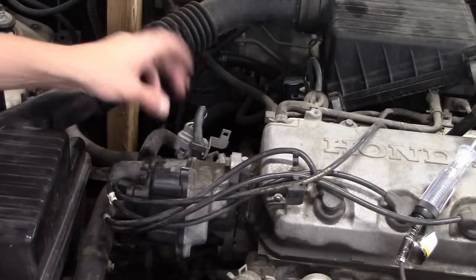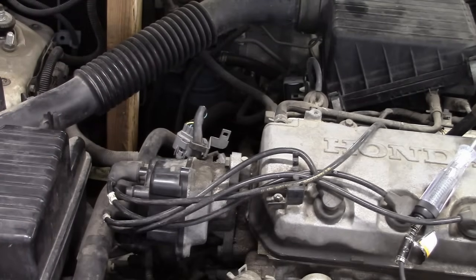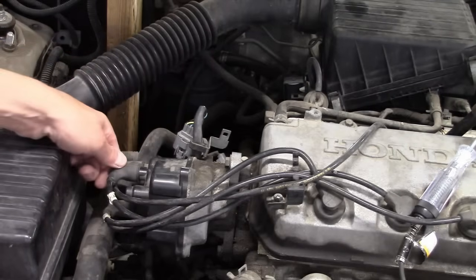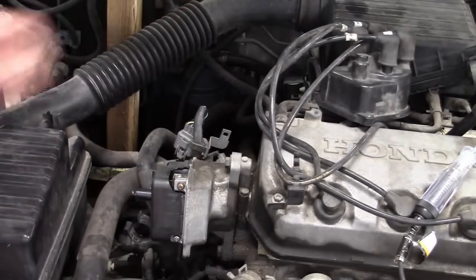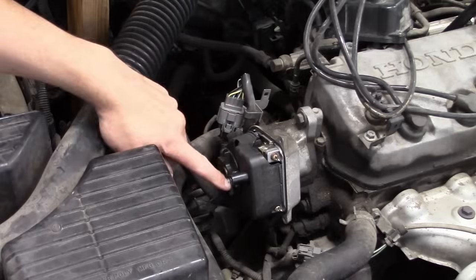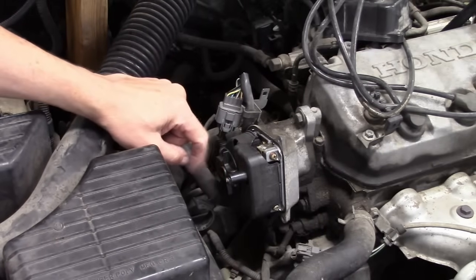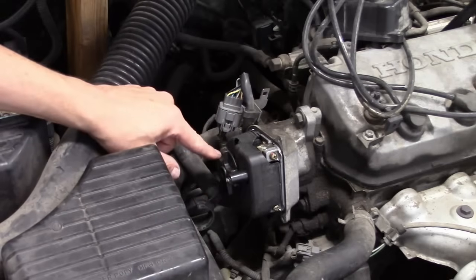And the first thing that I came across was a distributor. It did occur to me as one possibility: maybe there is some issue where we don't have rotation with the distributor. So, of course, I took off the distributor cap. I can see the rotor is right here. And it was handy having the kid around. As he was cranking, I would have him crank, and I could see the rotor was certainly turning.